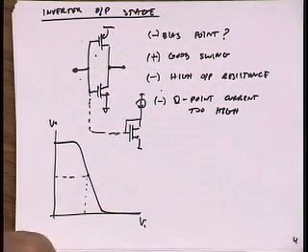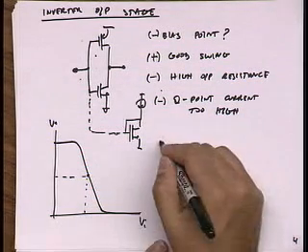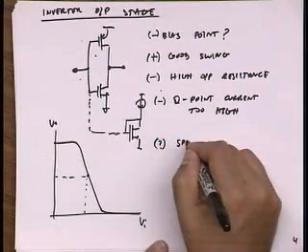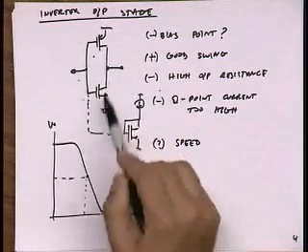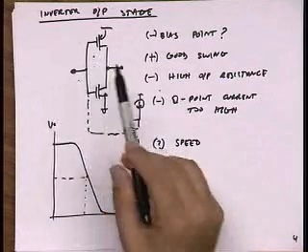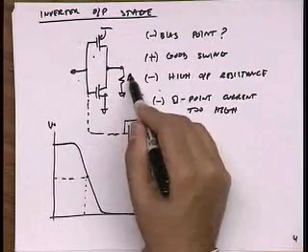Yes, Sang. It's going to be pretty slow due to Miller capacitance across. Yeah, potentially speed is an issue, right? So I'll put this in question mark because this is a common source stage. Its intrinsic gain is pretty high, but of course we're going to load it with some resistance.